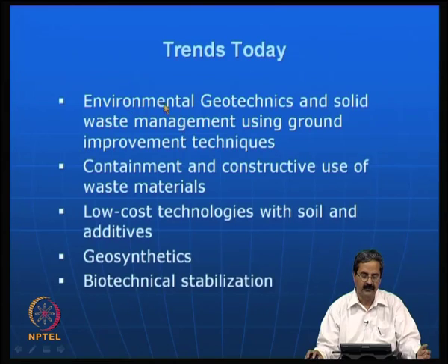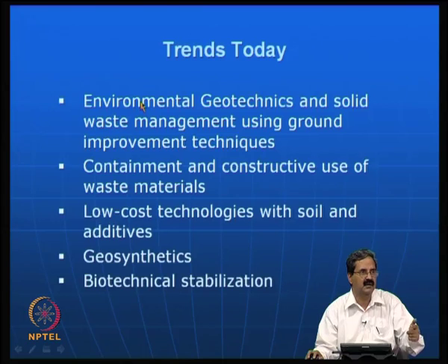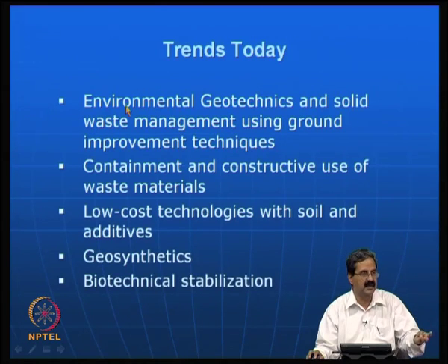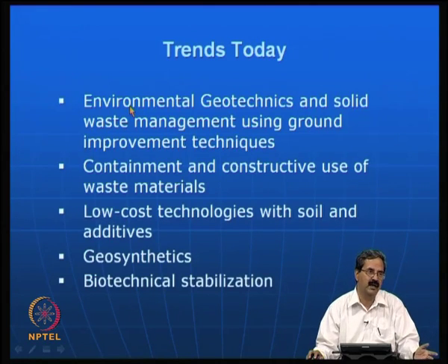What we call municipal solid waste, we try to understand the behavior of municipal solid waste and leachate compositions and their effect on buildings and foundations. If you have a leachate of very high concentration, it affects the concrete and steel. You construct a foundation, then it affects the concrete and steel, and it is going to be risky. So, you do not want that. The knowledge of environmental geotechnics is required, particularly in the understanding of compressibility, shear strength and permeability, some of the engineering properties, and also the quantity and quality of leachate, its long term and short term effects.